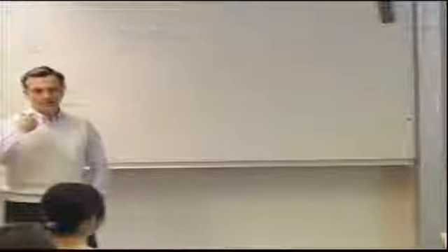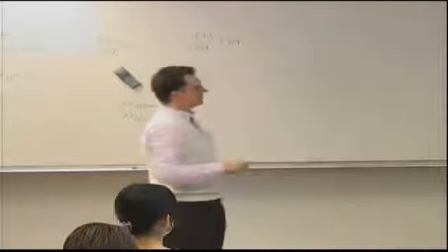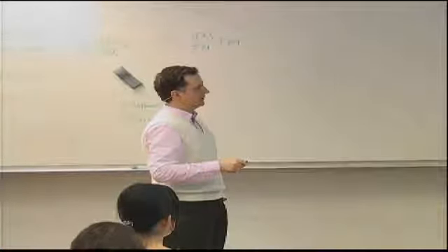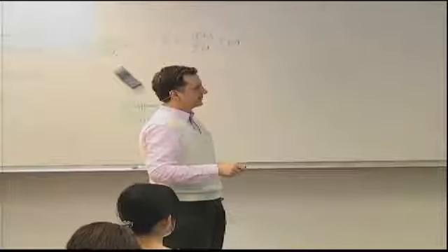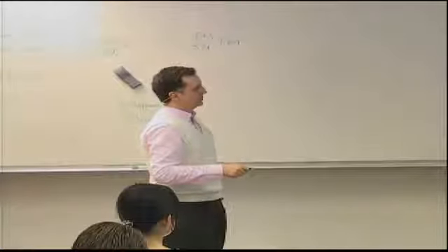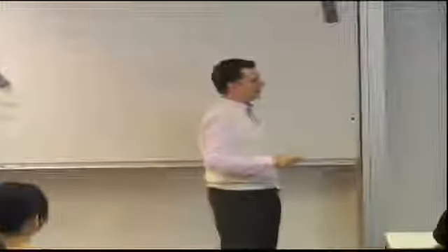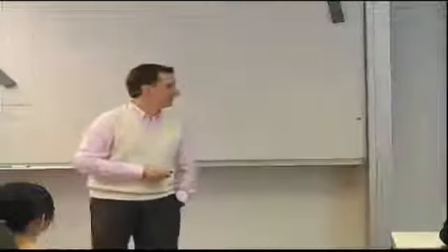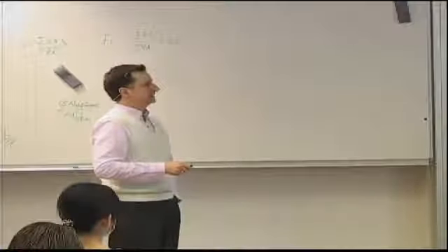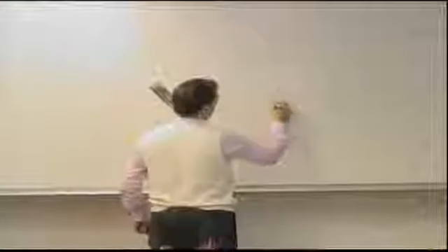Either C2 is 0, and then I will find that there is no out-of-plane buckling solution at all, or C2 is non-zero, and that means, because N0 and D11 are non-zero, I'm left with this sine of the square root of N0 over D11 times S equals 0, and that means that square root quantity must equal N times pi. So I can back-solve for N0 to get the well-known solution, N squared pi squared D11 over S squared. Now this is identical to our column buckling P critical equation, which says pi squared EI over L squared, L being the length, or in this case S.